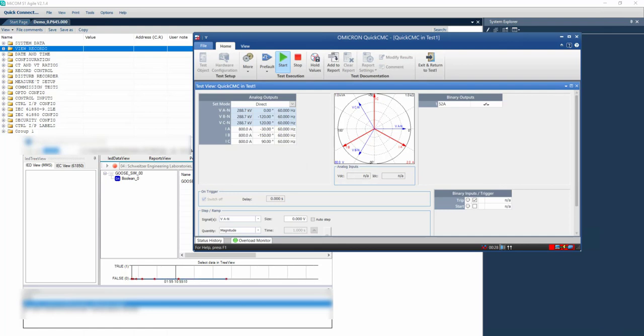As I said, it's like 100 GOOSE messages in just 4 milliseconds. So you can see here it's very fast. That means that the output from the test set is connected to that GOOSE message. So you can see here the information in the output. As I click up and down, you can see how it changes. Hopefully that's clear to you.